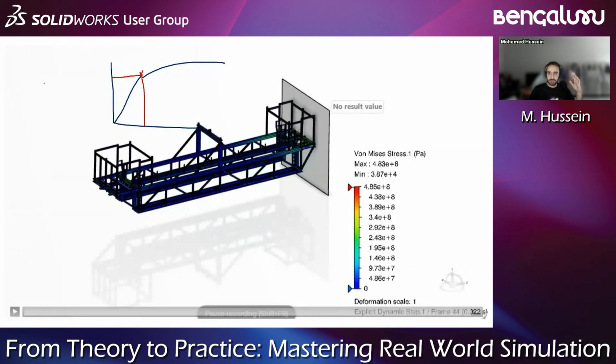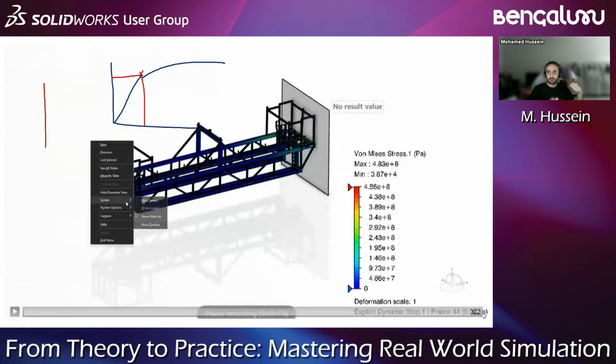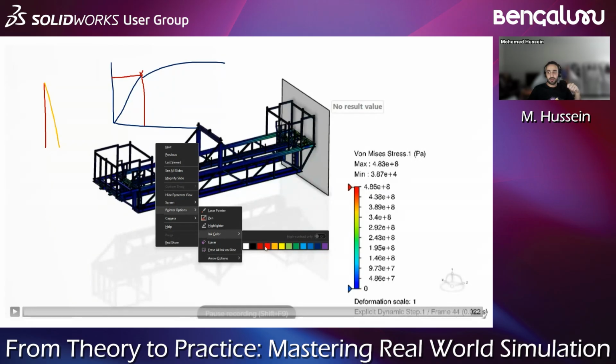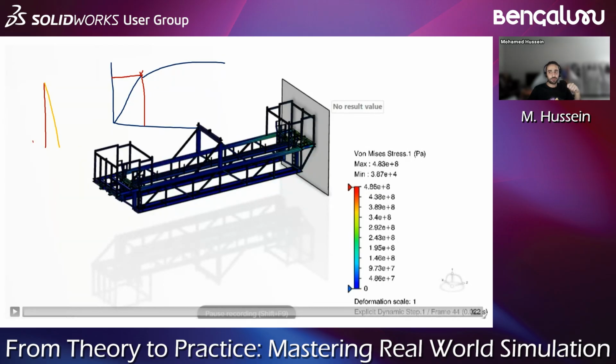So, for example, I have this beam this way. I applied some loads, and the result was that it became this way. But what happened after I removed the load? After I removed it, it goes back again to its original position, like nothing has happened. So this is the elastic region. What if I exceeded this region and moved to this area?